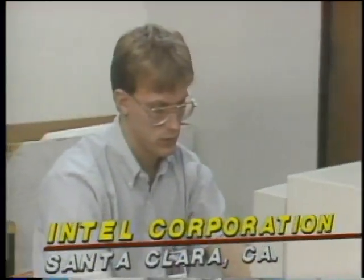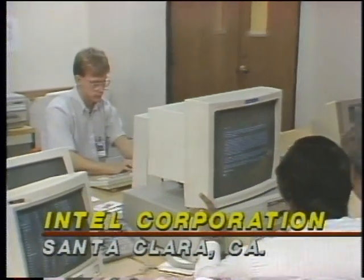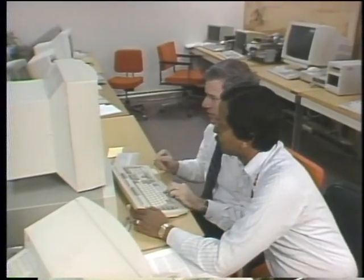Now, as Tim explained, we need memory management products because of the inherent memory problem in the original Intel 8088 processor. So we'll begin with a visit to Intel to find out more about the origins of the 640K barrier. The problems with accessing more memory started with the limitations of the original Intel 8088 processor. While the processor does contain over 1 megabyte of address space, only 640K was made available to DOS applications. The rest of the addressable memory space was dedicated to system ROM.